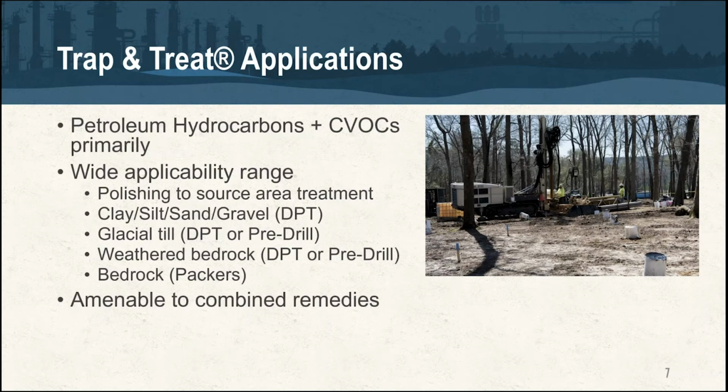I guess just to take one small step back to talk about carbon a little bit. When you're evaluating technologies that are activated carbon based, there are a couple things you need to keep in mind. One is the box you have to check: make sure they're not using regenerated carbon. I think most companies aren't, but there's some use of that here in the US. Two is the source of the carbon itself. The properties of, say, a coal-based carbon or a coconut-based carbon are going to be different, so it's not an apples to apples comparison.